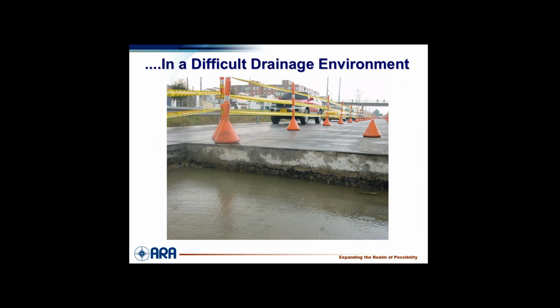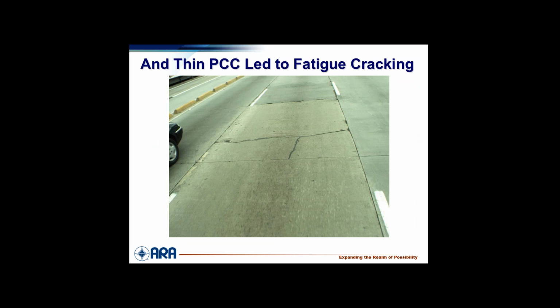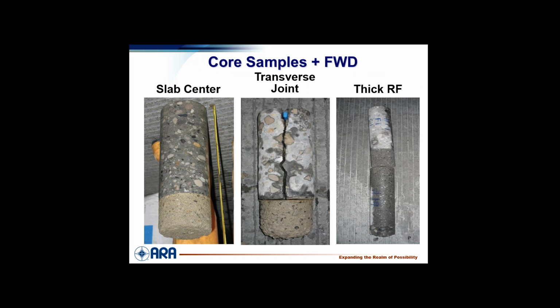And whenever they start replacing slabs, you can see here's your slab, your flowable fill, your asphalt, and then just a bathtub in here. And it creates cracks, which then create corner breaks. There are dowel bars, but that was, thank God they did that, or this would be infinitely worse. And here, from the center of a slab, it really bonded well, but when you get near the joint, it's eroded, and you can see some of that has gone up and out of the joint.